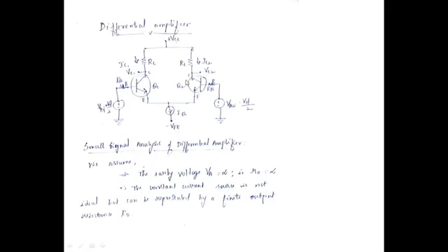So your VCC and VEE are short circuited, and the remaining part is drawn with VB in series with RB. We replace the transistor Q1 by its transistor parameters, where between the base and emitter a resistance R pi is present, and the voltage across this resistance is V pi 1.